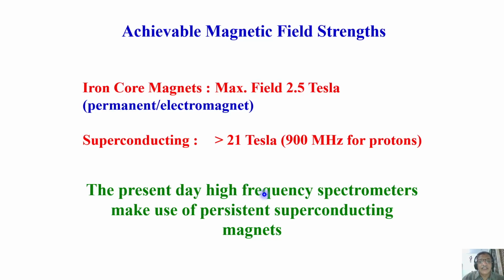So long as you maintain the liquid helium temperature, with the coil immersed in liquid helium at the cryogenic temperature, the magnetic field always exists, because the current you have passed once keeps on moving. Current will always be present. It is called a superconducting state. That means there is no opposition for the flow of electrons. The current, once you pass and generate the magnetic field, persists forever, so long as you maintain the superconducting temperature.